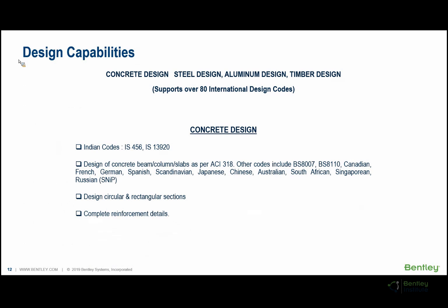If we come to the design section, for concrete design we support IS 456, the Indian Concrete Code. We also support IS 13920 for ductile design, and in the latest STAAD.Pro release we have also included the latest IS 13920 2016.